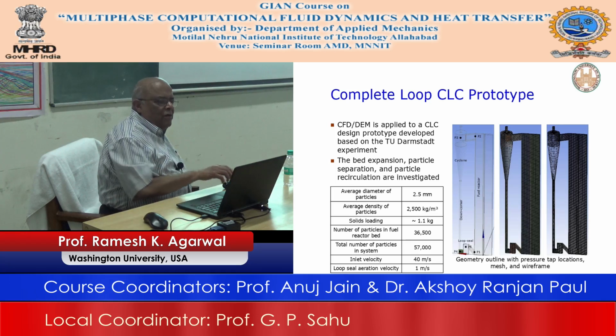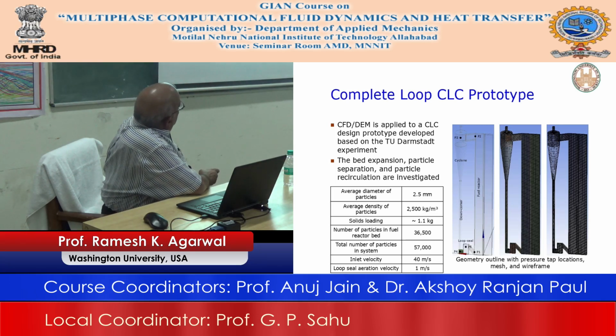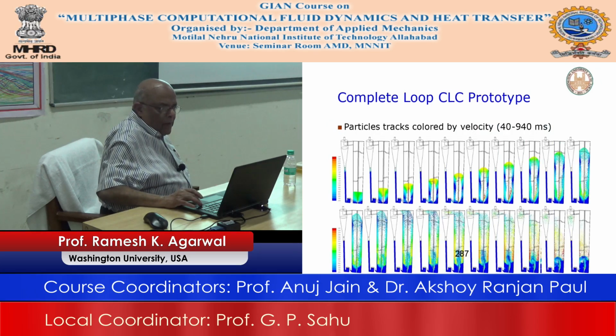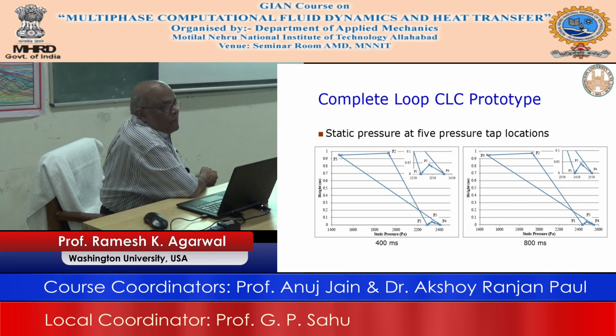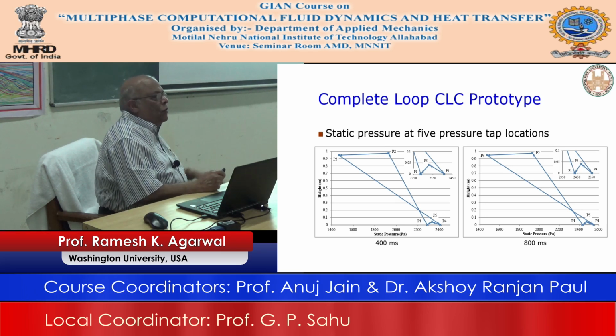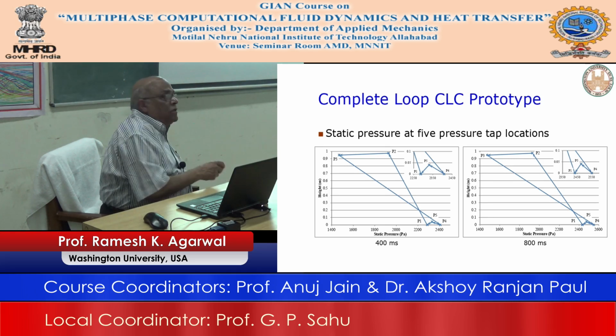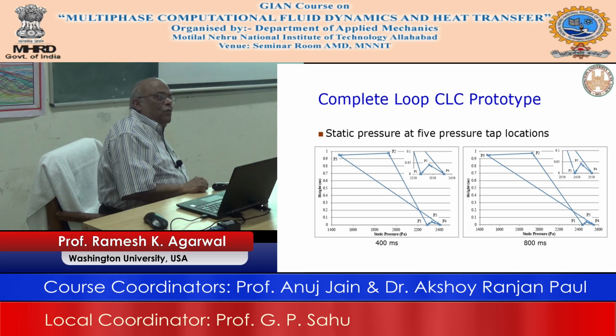All right. So, we basically took this, and the first thing we did was ask what the pressure is at different locations of that particular setup. So, now P1, P2, P3, etc., are the pressures at different locations. By CFD we measured the pressure difference from various places numerically. This is the area which shows the pressure where the loop seal is and where the whole thing was getting stuck. We found that these pressures were very, very small. So, that is why it was not moving.